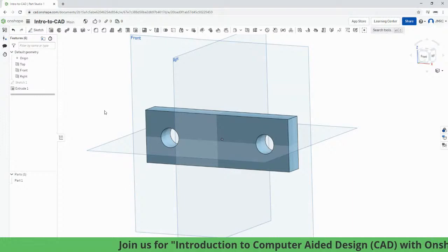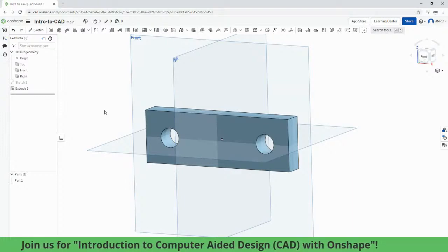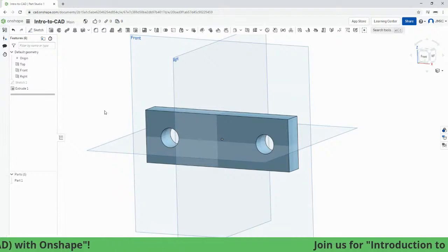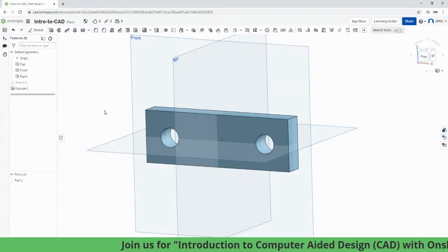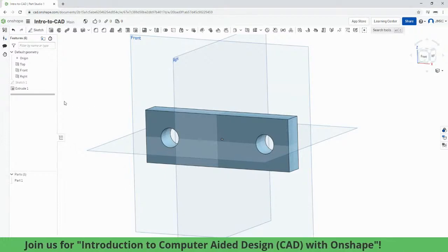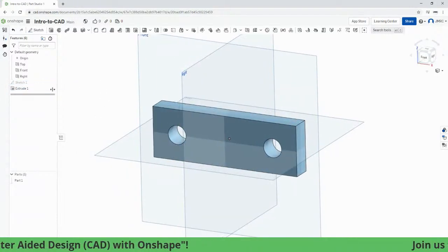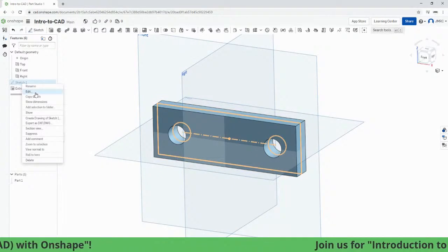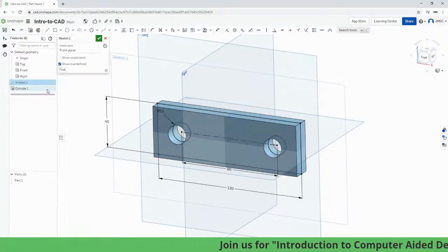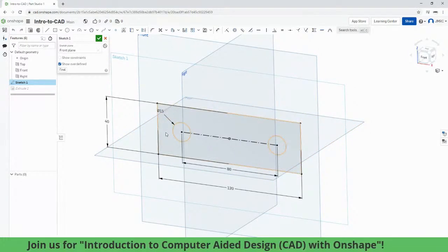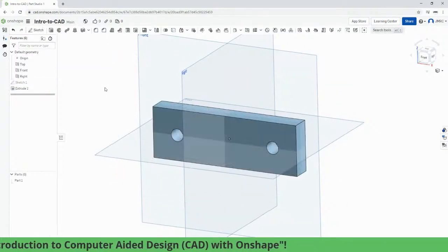In addition, I want those who are absolute beginners to take note of how sketch constraints, dimensions, and features relate or stack up to one another. I'm going to revert back to the previous dimension, heading back to Sketch 1, right click, selecting edit, double click on this 15 diameter, keying in 10. Hitting the green check mark.